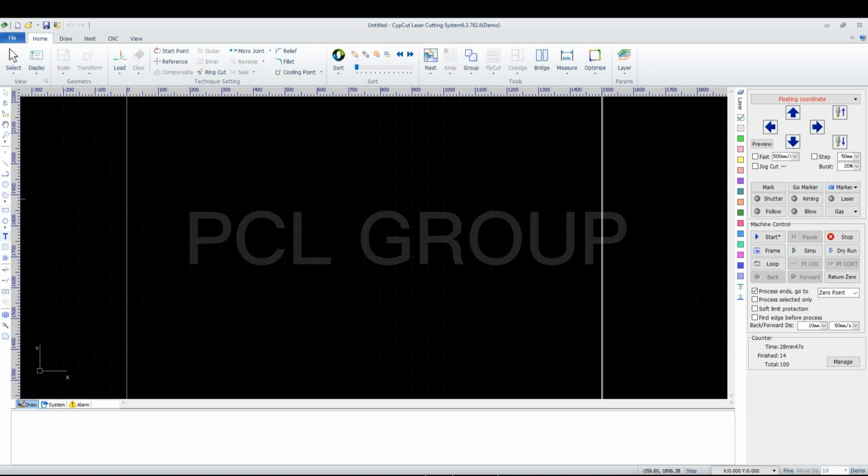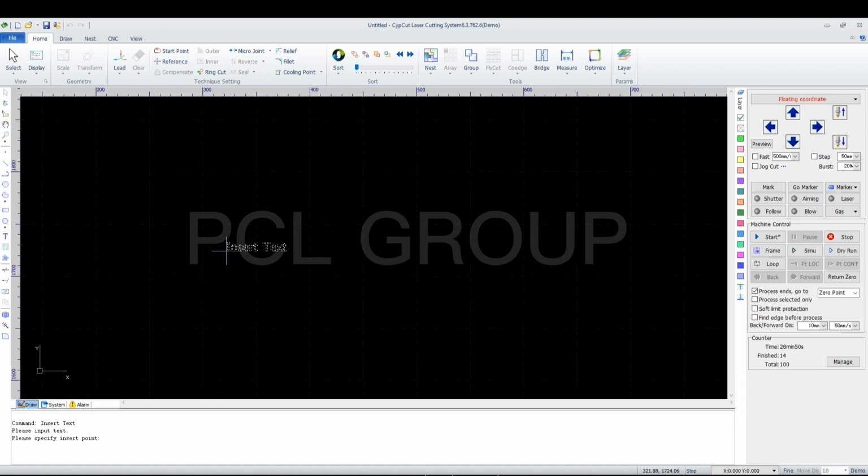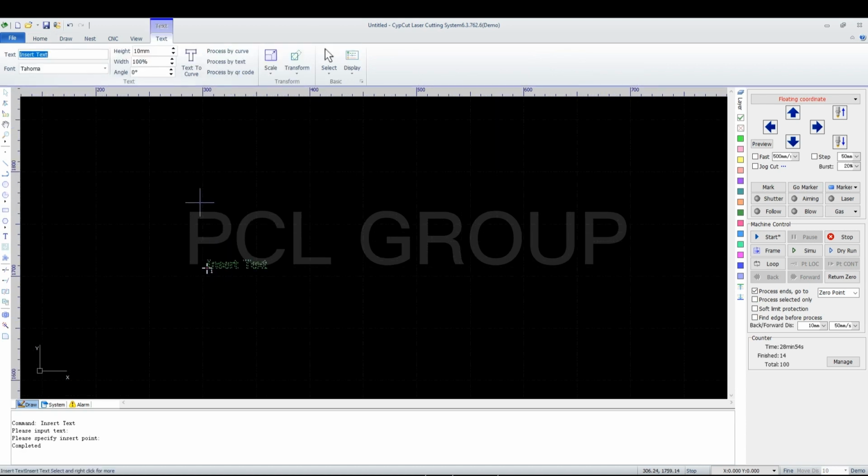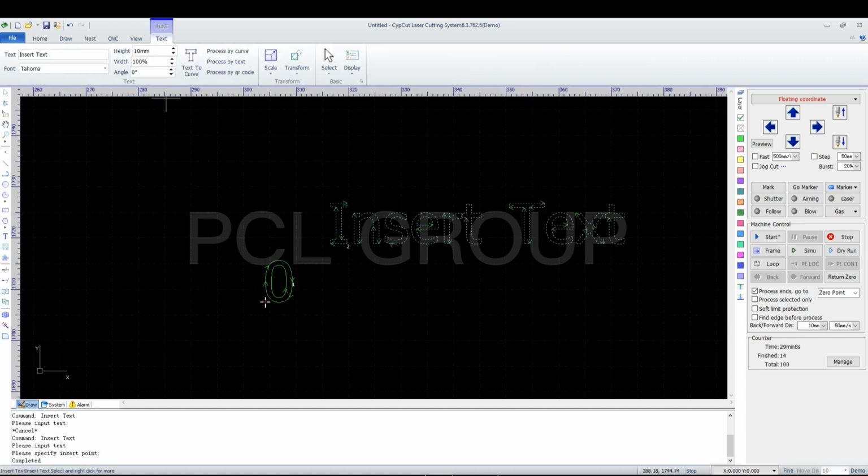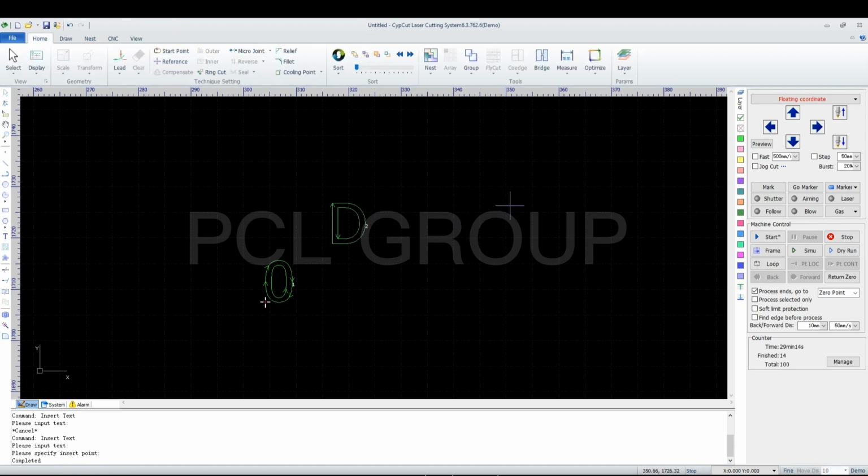For instance, if we got the number 0 and the letter D, if we don't get it bridged, both of the round and the ring would fall down, and only leaves a single hole on the metal sheet, which wouldn't be satisfying.